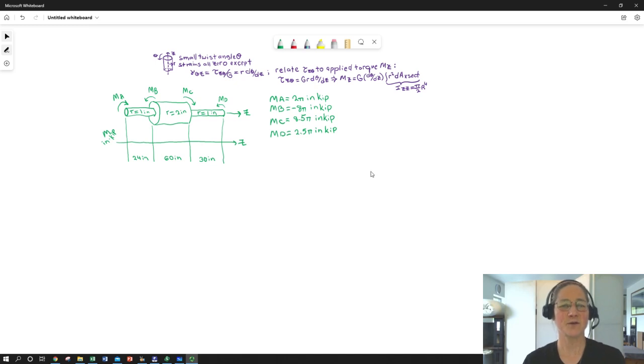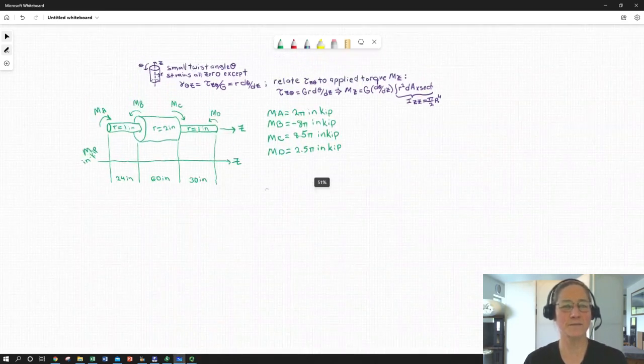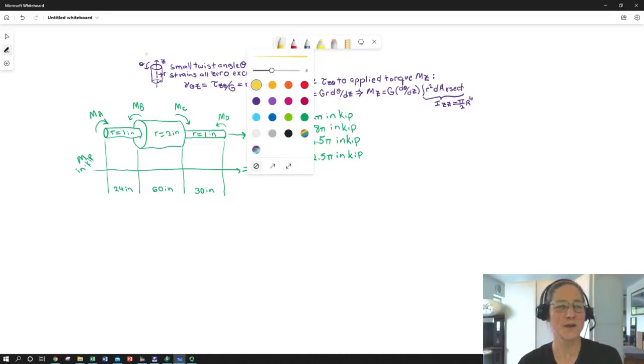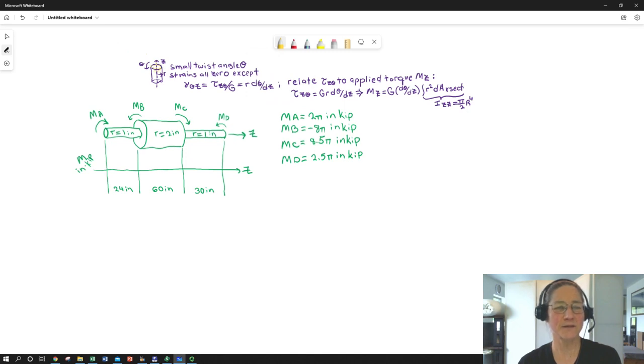But before we dive into it per se, we're going to just go over some of the great equations that we can derive. So if we have a cylinder with the z-axis running up the center, we can define an orthogonal set of axes and a coordinate system for that shaft. So we have z in the axial, r radial, and then we define theta as a circumferential or tangential direction. So instead of x, y, z, we have r, theta, z.